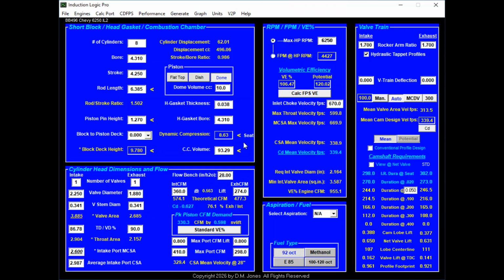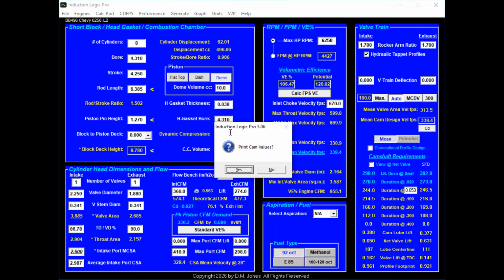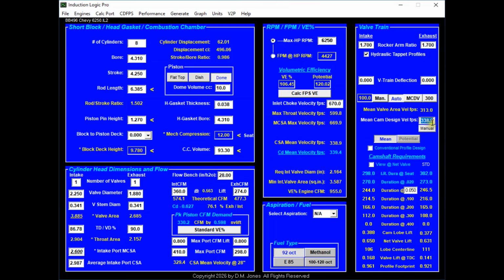While using the valve seat duration tells you exactly when the valve mechanically closes, some experts argue that cylinder pressure overcomes the intake port charge column before total closure occurs. As a result, they calculate the intake valve closing point using either 20 thousandths or 50 thousandths valve lift duration instead. Each of these calculation methods results in vastly different dynamic compression ratio values. Furthermore, each method requires its own acceptable target range based on the fuel octane, cylinder head material, and combustion chamber design.